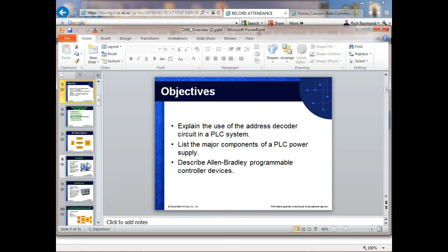You understand? So they came out with something called PROM. What's PROM? Programmable read-only memory. This basically is a one-shot deal. We could program it in a programmer, but once we program it the first time, we couldn't pull the chip out and reprogram it. We definitely can't program it inside the unit it's intended to operate in. So we have a special unit called a PROM programmer, and we've got one around here somewhere, guys. But it's a one-shot deal.